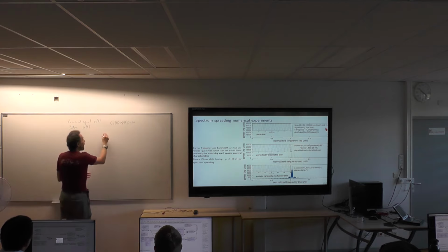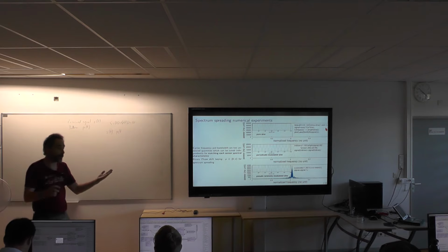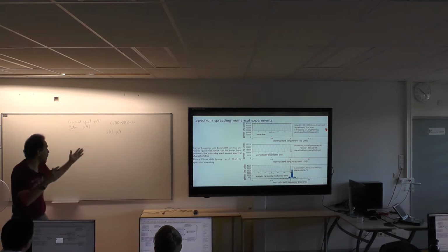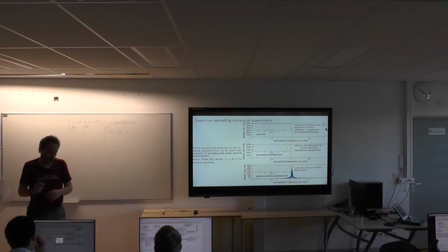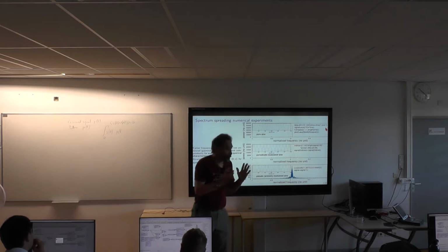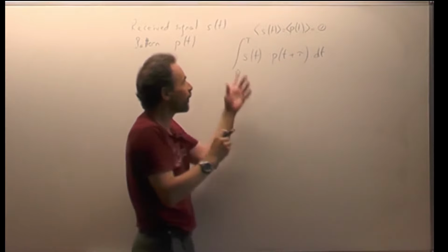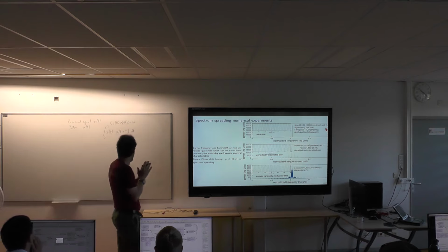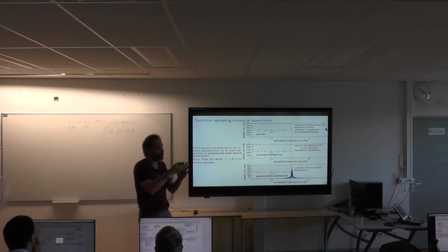So the mean values are 0, so half of the samples are positive, half are negative. If you multiply your signal with the pattern, sometimes you get positive times positive, which is positive, sometimes positive times negative, which is negative, and on average the sum of this product cancels out. If we want to average, we integrate over the duration of a pattern. Most of the time these quantities will average out, except if you shift the pattern over the signal that you received. If I shift the pattern by a quantity tau and integrate over the duration T, maybe there's a time delay where the pattern matches the copy that is broadcast in the signal, and then negative multiplies with negative, becoming positive, positive multiplies with positive, and you see that energy accumulates.